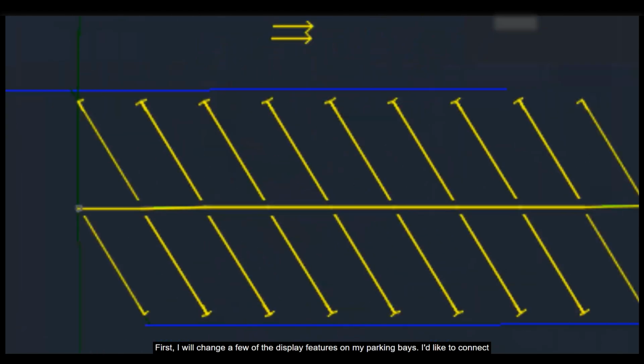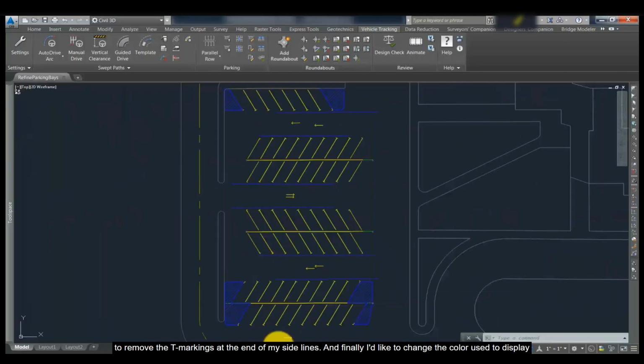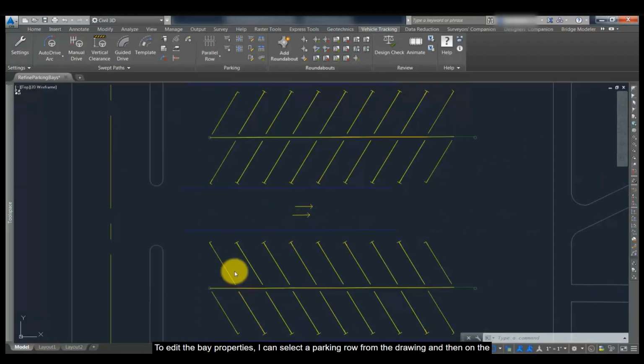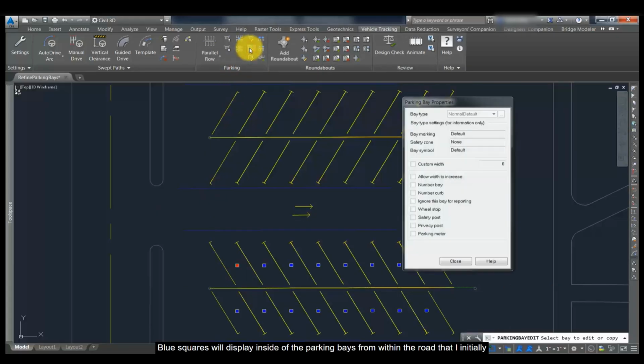I would like to connect my bay side lines to the end lines so there is no longer a gap between the two. I would also like to remove the T markings at the end of the side lines, and finally I would like to change the color used to display the parking bays. To edit the bay properties, I can select a parking row from the drawing, and then on the parking panel I can select edit parking bay.